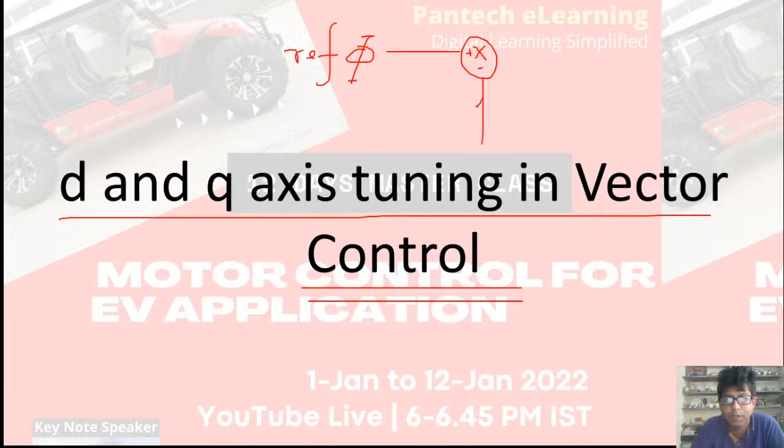Flux is produced through the stator direct axis current. So this feedback I am taking from the stator direct axis current, which is coming from the ABC to DQ transformation. Then there is a PI regulator, and this is generating the stator direct axis voltage.